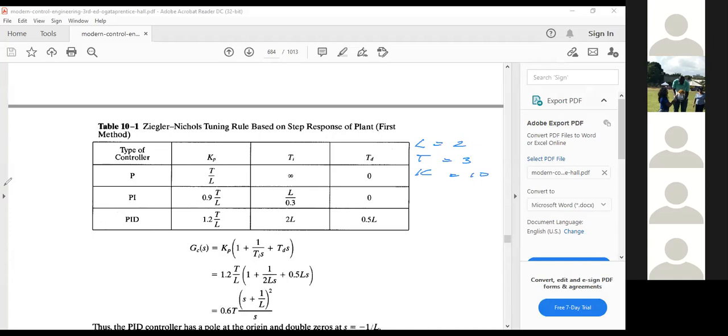Let us say that we had a furnace. My favorite example, my go-to example. Which one of these three would we use? The P or the PI? We always go with PI. We never normally go with P, no matter what, even if P would have worked.